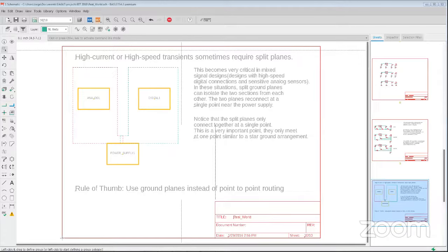How much do things change when adding multiple layers, 8 to 12? It depends on the signal you're routing. As you know, a signal can be considered basically a microstrip in the simplest case, where you have a ground plane underneath a trace on the top layer. As you add layers, if you're going to maintain the same thickness of the overall PCB, the individual layers thin out.